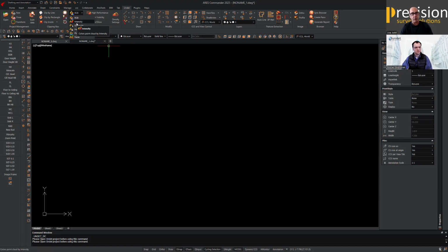And as we know, when you're trying to digitize from a point cloud, not all one intensity shows things, so you need to manage that intensity ramp slightly just to bring out other details in the data that's collected. You know, a white background wall with a white feature on it tends to look like it's the same intensity. And there are some tools in here to allow you to manage that visual aspect of what you're looking at. So that was a neat option.